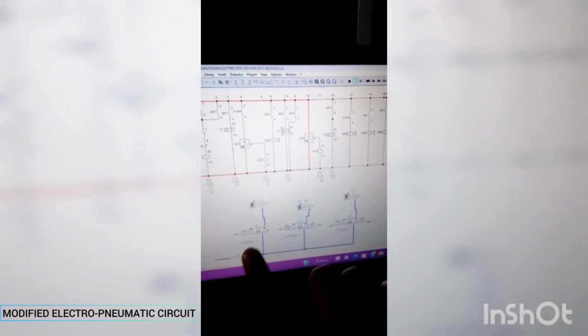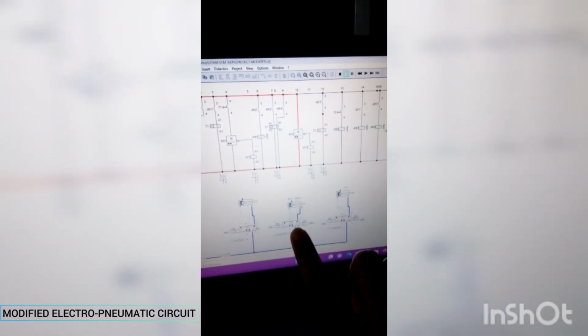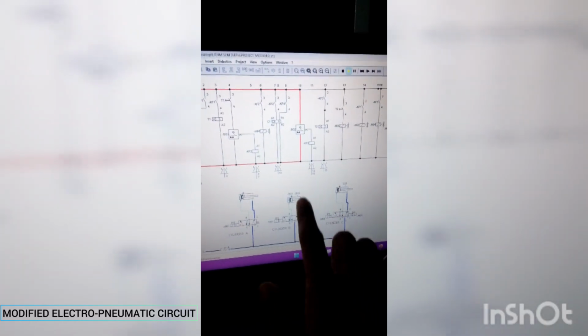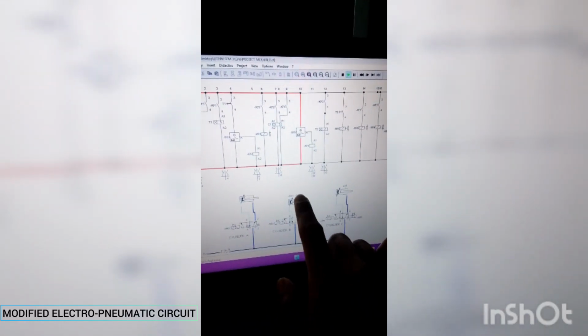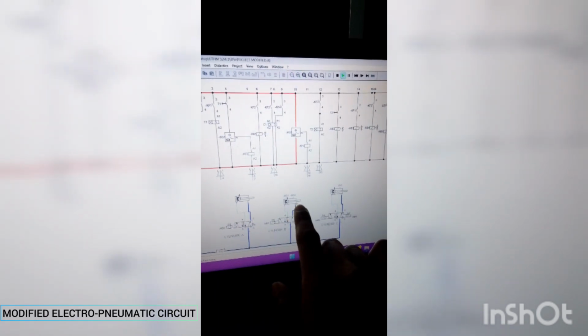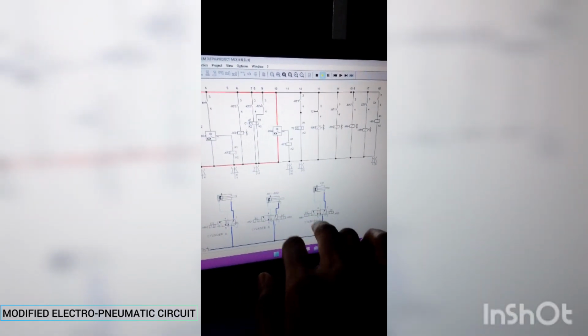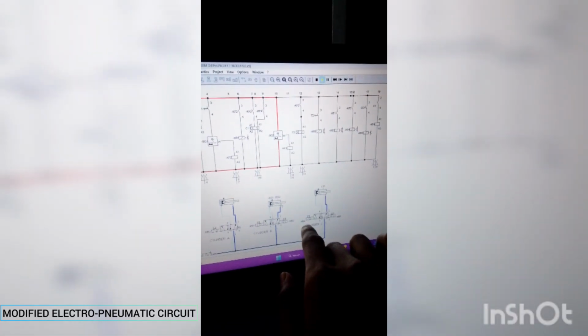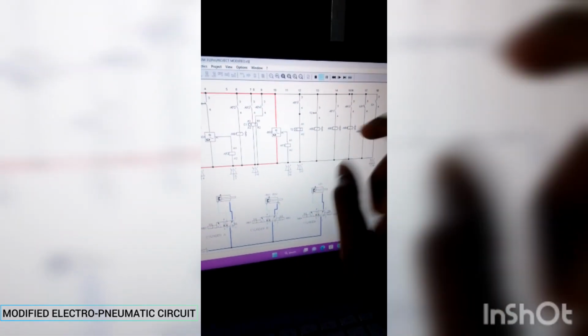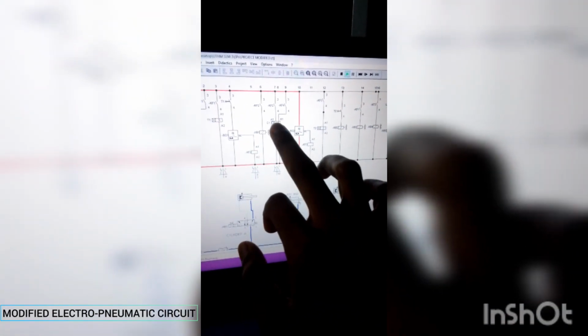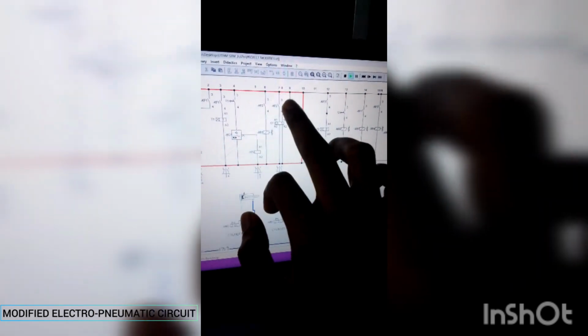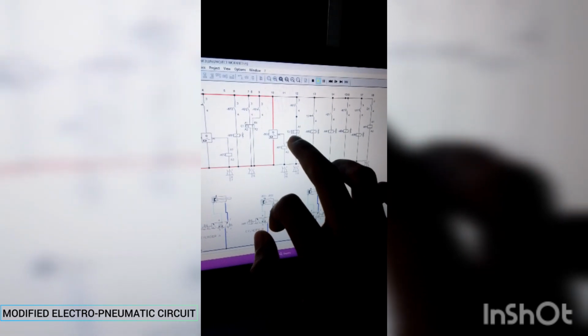So like I said, once this negative BG2 sensor detects the presence of this rod cylinder, it will automatically make cylinder C extend, because of this negative MB4 solenoid valve here, and this contact relay will activate. This counter will be activated by this contact relay, which is energized. This coil relay will be energized by the sensor, which will activate this contact relay, same together with this timer.